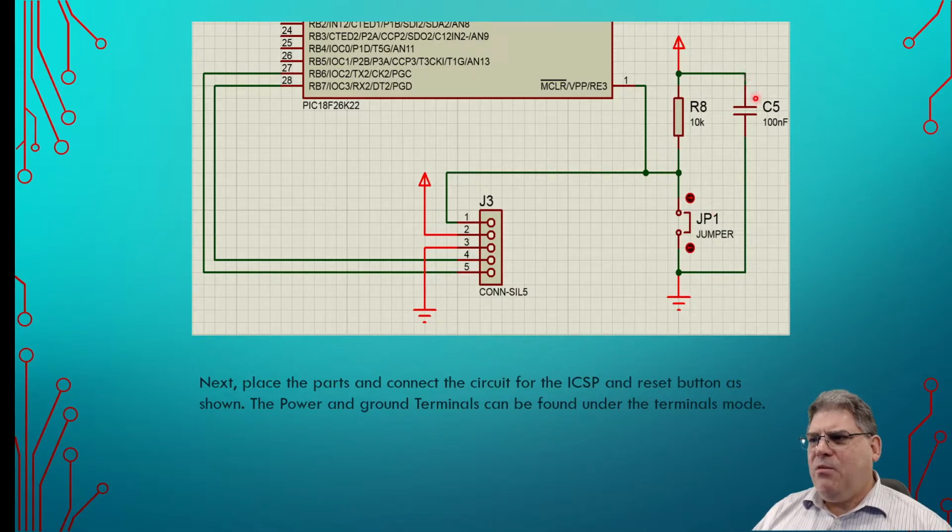All right. Again, we have a bypass capacitor here. This is going to want to live as close to the chip as possible. And so that's why I drew it in here. I like to draw mine in very tight with the chips the way I intend them. Quite often you'll see in larger designs, they will have banks of capacitors that are all the decoupling capacitors, and they don't specify which one goes where. For a small design like this, I really like to have the component, in this case C5, living in the same little bit as the chip. All right, again, pause the video if you need some more time.